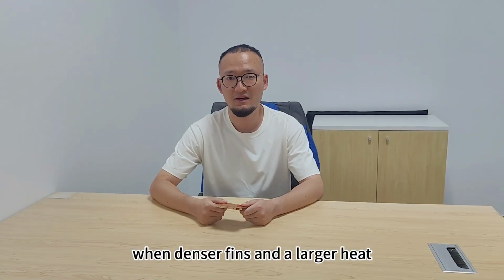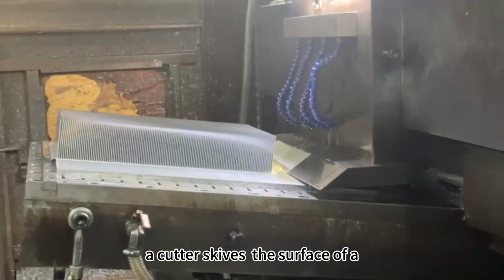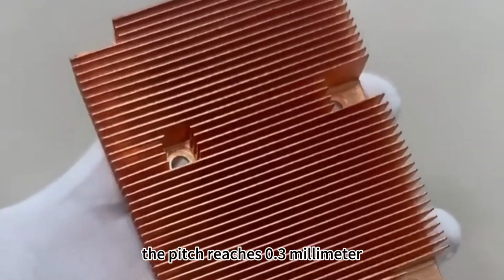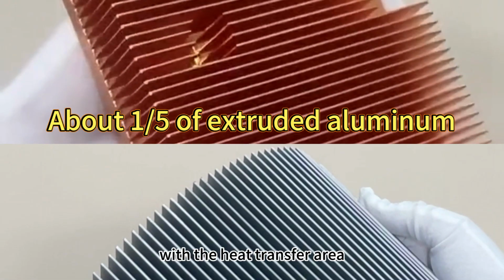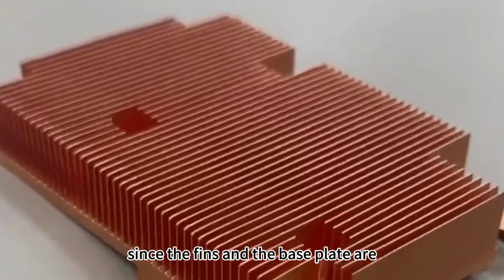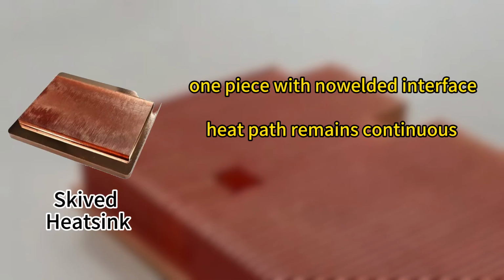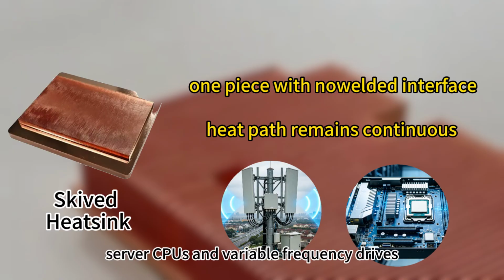Denser fins and a larger heat transfer area are required. Scaled fin technology comes into play. A cutter skives the surface of a solid aluminum block directly, bending the chips upright to form fins. The pitch reaches 0.3 mm, about 1/5 of extruded aluminum, with the heat transfer area increased by 3 to 5 times. Since the fins and the base plate are one piece with no welded interface, the heat path remains continuous. Typical applications include base station RUs, server CPUs, and variable frequency drives.